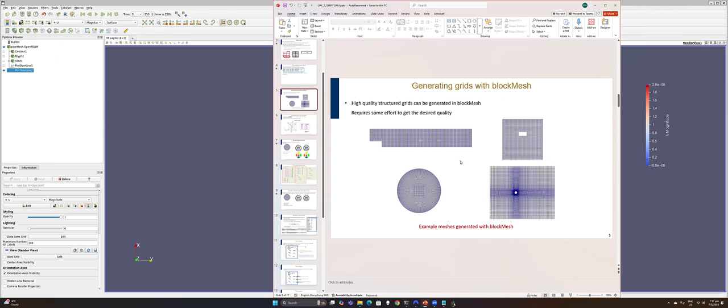By the way, you don't necessarily have to use blockMesh to generate your mesh. You can generate your geometry in any of the CAD tools, but just save it as STL. Please investigate a little bit on this when working on it. That would be more of the next level, but we haven't been able to cover that. You would then use it in snappyHexMesh if you don't have a mesh generation tool. That's what you would use to generate your mesh if your geometry is really complex.